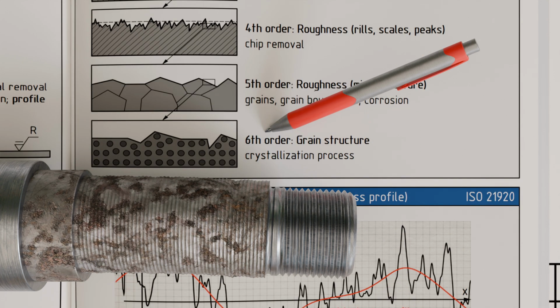These microstructural roughness features are called fifth-order geometric deviations. One order of magnitude smaller leads finally to the atomic structure of the microstructure and thus the lattice structure of metals. Even such a lattice structure is not ideally formed but contains defects. These atomic deviations from the ideal lattice structure are referred to as sixth-order geometric deviations. These deviations are influenced by the crystallization process during solidification of metals.